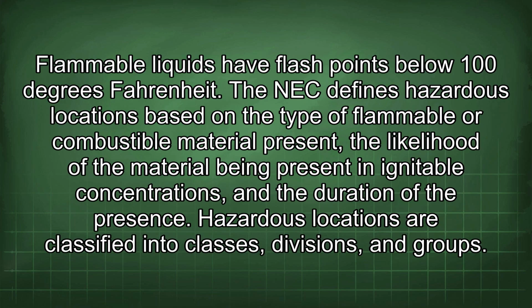Flammable liquids have flash points below 100 degrees Fahrenheit. The NEC defines hazardous locations based on the type of flammable or combustible material present, the likelihood of the material being present in ignitable concentrations, and the duration of the presence. Hazardous locations are classified into classes, divisions, and groups.